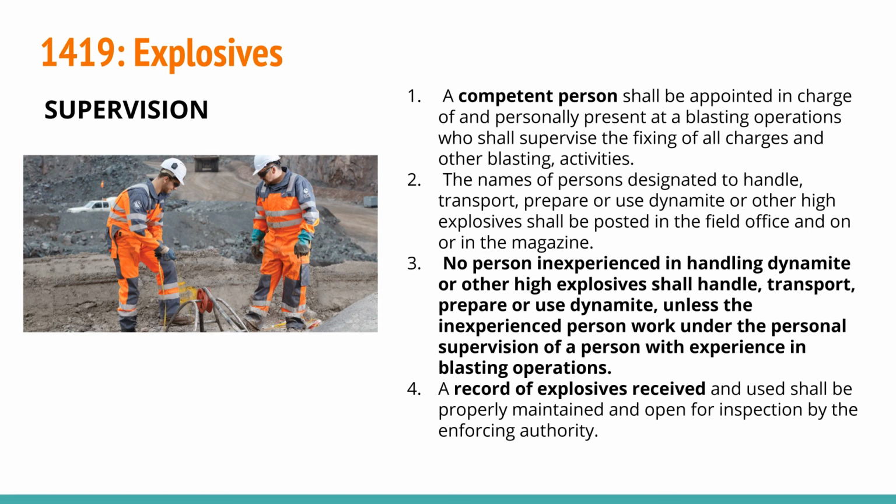Importantly, no inexperienced person should handle dynamite unless the inexperienced person works under the personal supervision of a person with adequate experience. Lastly, a record of explosives received and used shall be properly maintained and open for inspection by the enforcing authority.